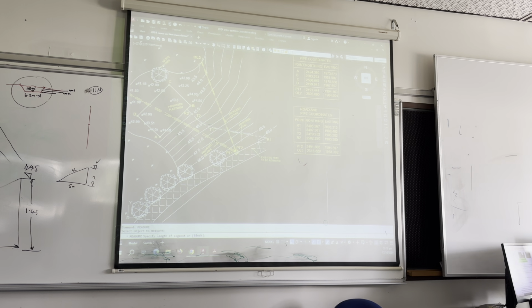So I'm going to click on here, and down the bottom it's asking for the block, B, enter. The block name is called cross, enter. Measure, yes. I want it to, when I align it, go round and align itself at right angles to it. So Y, enter. And the measured length is 5 metres, enter. And there we are, it's on there now.